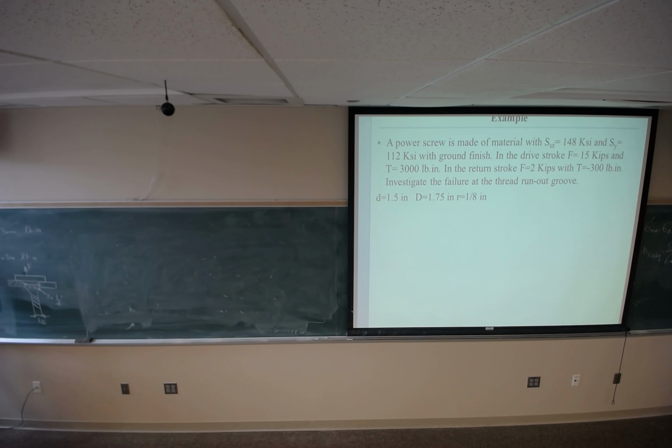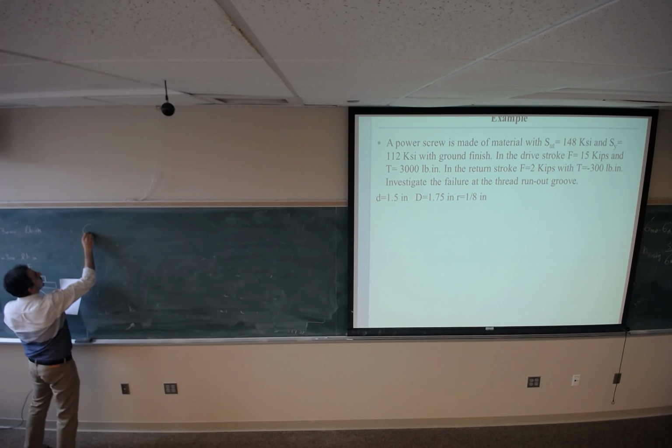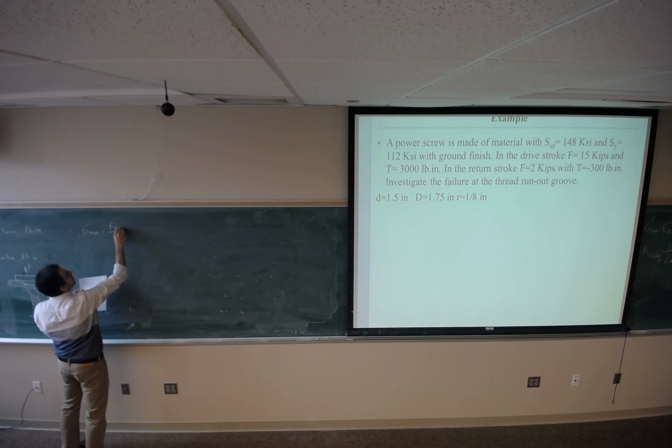So this force is making the axial load, and this torque is making the shear stress. So sigma max is going to be F max divided by area.